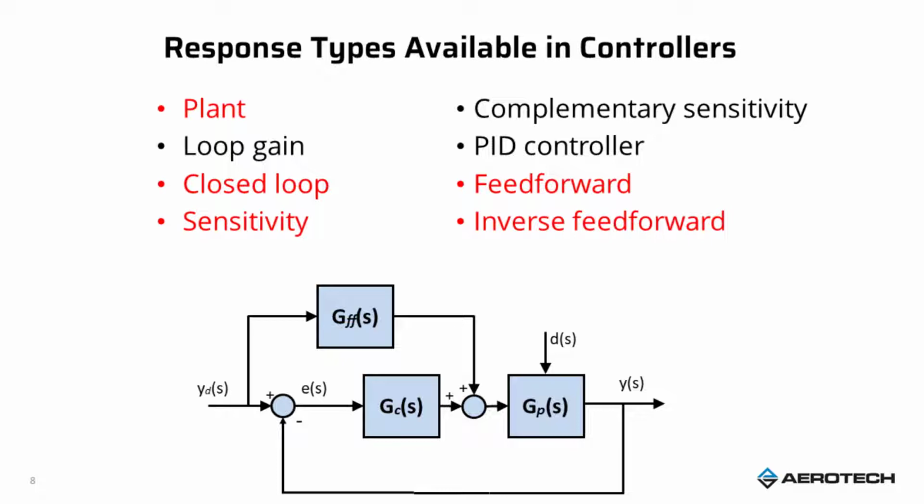So I have a system here. You'll notice that this differs from the first block diagram I've shown: I'll just assume unity feedback, so H of S is equal to 1. And I have the same plant, GP of S, and the same control law, GC of S, which is usually a PID type controller. And we've added in the feed forward transfer function, GFF of S. It takes its input from the command and is inserted before the plant and after the control law.